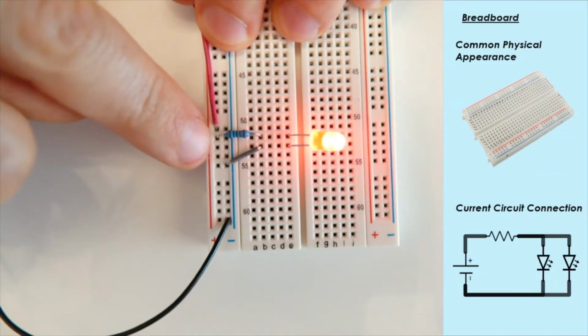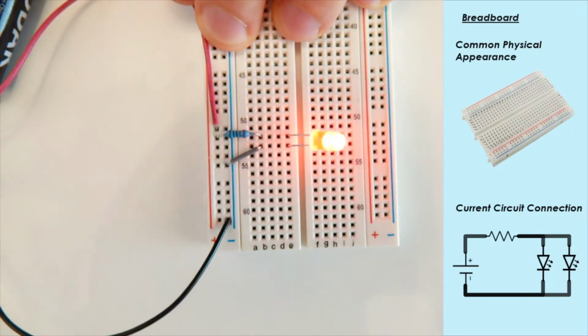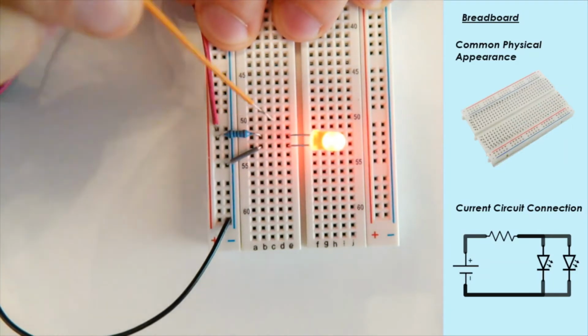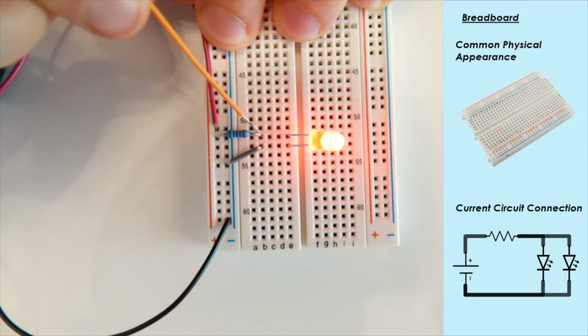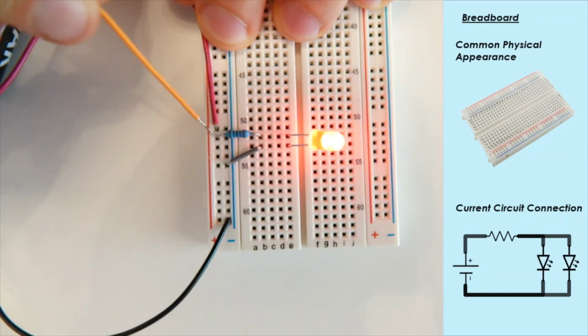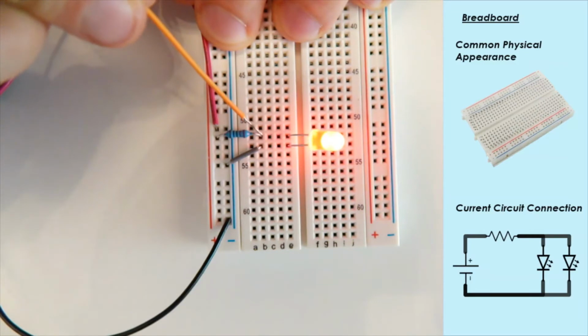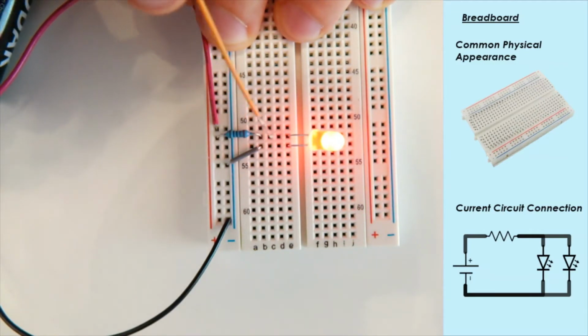We then use this resistor, which is connected here, to bridge across to this row here, where we come across, and if you look at the diagram, we connect the positive end of our battery along the resistor. Then we find the resistor is connected to the positive leg of our LED. And so we've connected the anode of our LED into this point here, which is now on that shared rail. And that goes across onto the next line here. The negative side of our LED is now connected to the negative side of our battery.